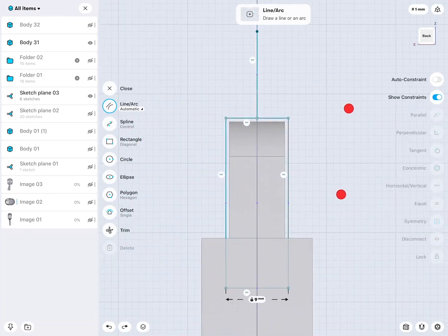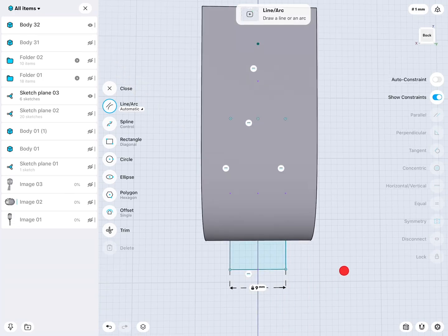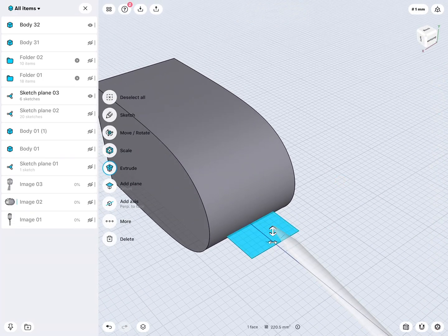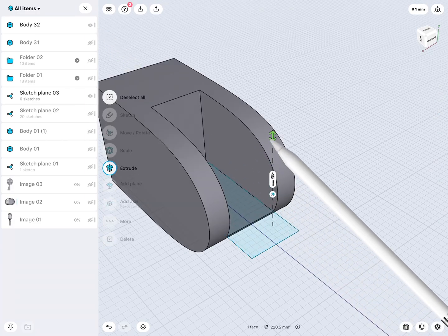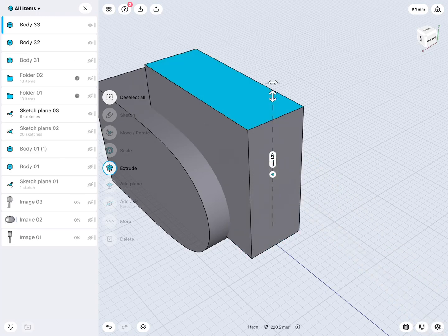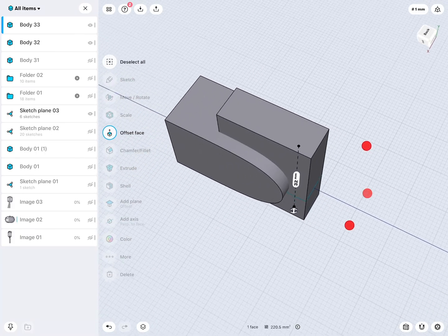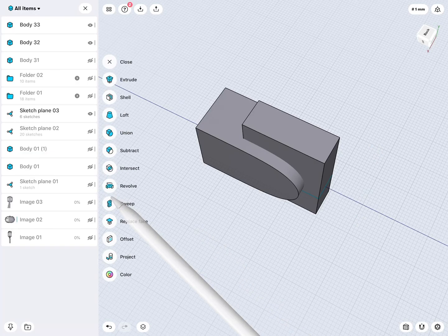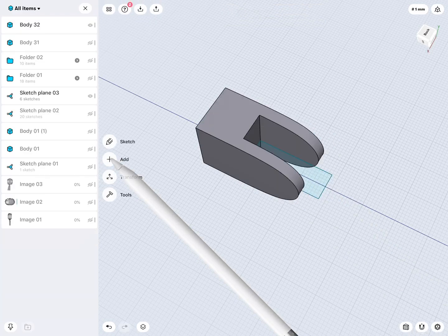So you see, I don't really use much of measuring. The grid is just so perfect to do all these measurings while you are modeling. Okay, and the reason why I created the sketch is I use it to cut this open. Actually, I do a new body, extend the body, and then go to subtract and say from this, remove that one.